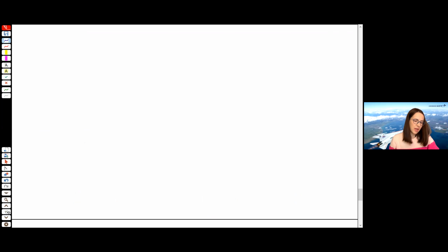Okay, so we just used table D sub S to get the relationships across the normal shock. We're now going to plug in using the values we found. So our downstream static pressure is 15 psia times 3.613, right? That's the number we just got from the table. So it's 54.2 psia.